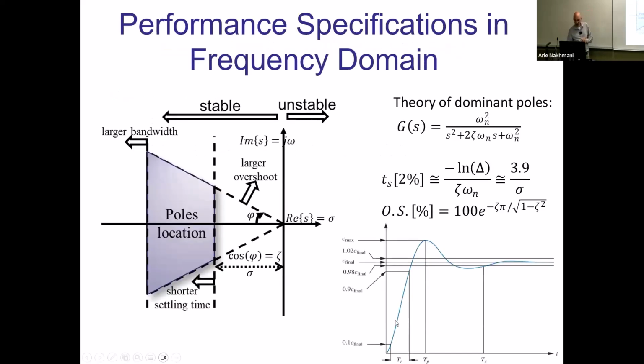And then you will get some sort of function like that, right? So you'll have the blue step response. You can measure the value of the overshoot. You can measure the value of the settling time. And based on these two formulas, you actually can compute these parameters back, which means this will give you the transfer function just from step response.